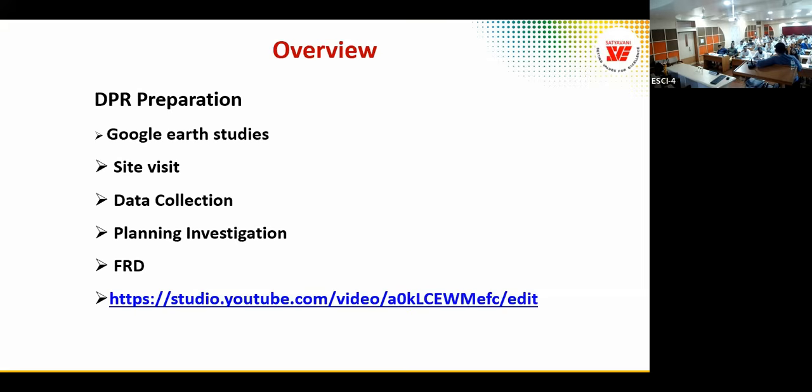Though we did the investigation, we took a decision: next time onwards, we should not allow the RQD test to be limited. It should be in parallel with the normal investigation. What is the depth for RQD? Whatever it is, suppose I have a 20 meter basement, the RQD should be 30 meters, 10 meters beyond the minimum depth of foundation, 10 meters beyond the foundation depth.